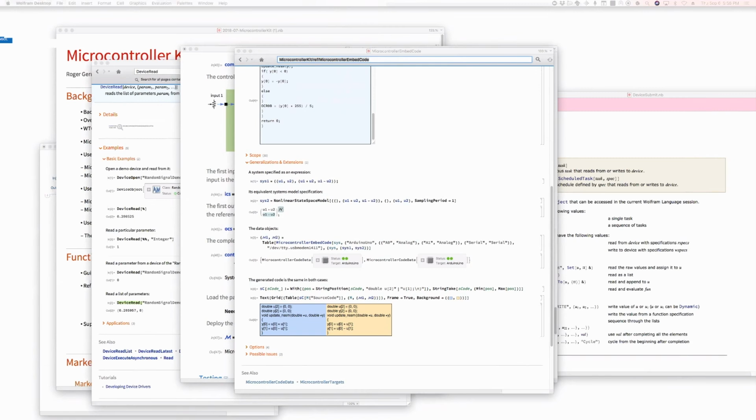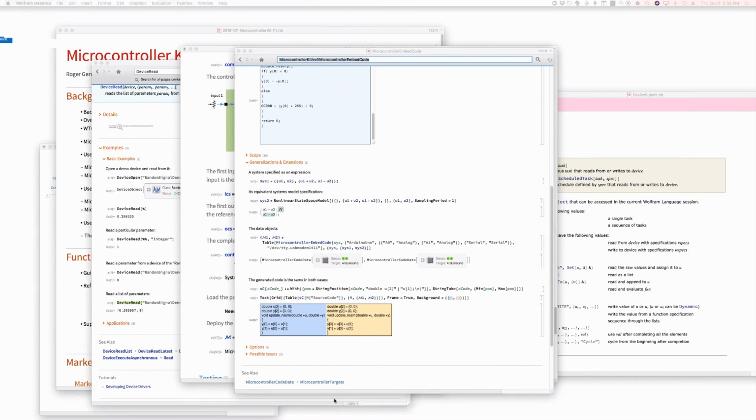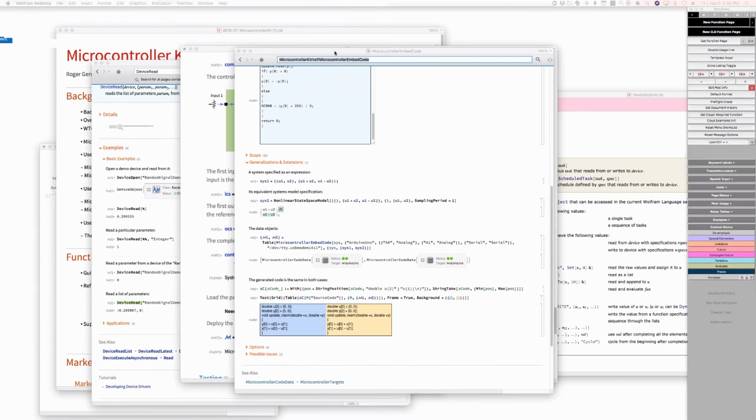But in modern times, if I'm understanding, people are trying to build generalized microcontrollers that have neural nets inside them. Is that true? Yes, but a little bit bigger machines than 8-bit. I think there are people who are trying to do 8-bit neural nets, but that's a different story. What you do today, if you're going to run neural nets, is that they often have a functional block, and you have to be able to convert your neural net model into a language that's understood by that block.